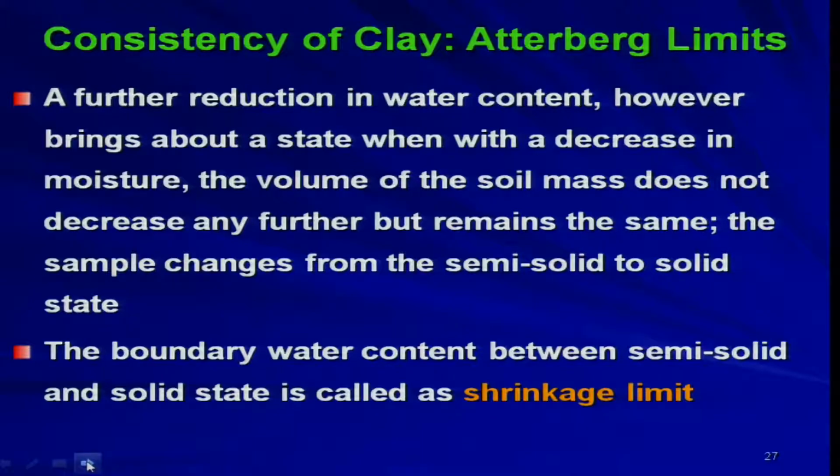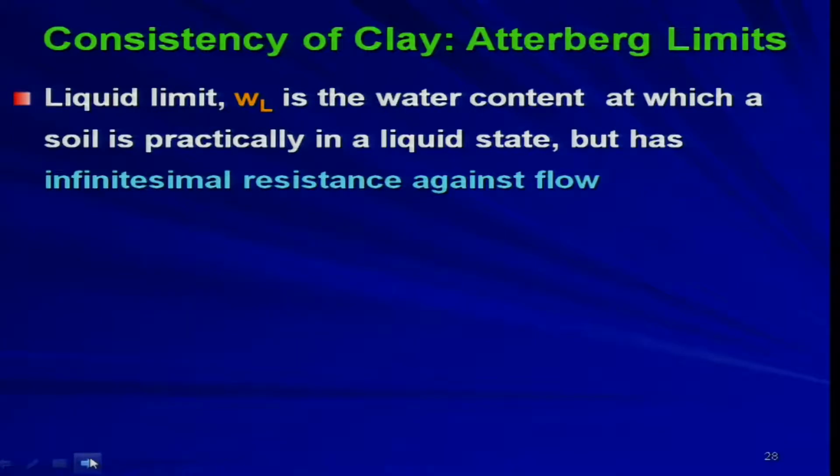The boundary water content between semi-solid and solid state is called the shrinkage limit. So, this is the boundary between semi-solid and solid state. That means between the shrinkage limit and plastic limit, the soil will behave in a semi-solid state. Now, liquid limit can be defined.